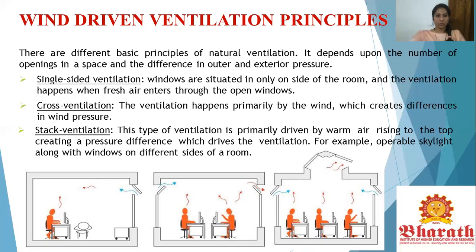It depends upon the number of openings in a space and the difference between the interior and exterior pressure. It's about how these temperature and pressure differences and the wind act to create ventilation. In this subcategory, you would see single-sided ventilation, cross ventilation, and stack ventilation. As you can see in the given figures below, they try to clarify what these things mean. So in the first image, you can see single-sided ventilation.